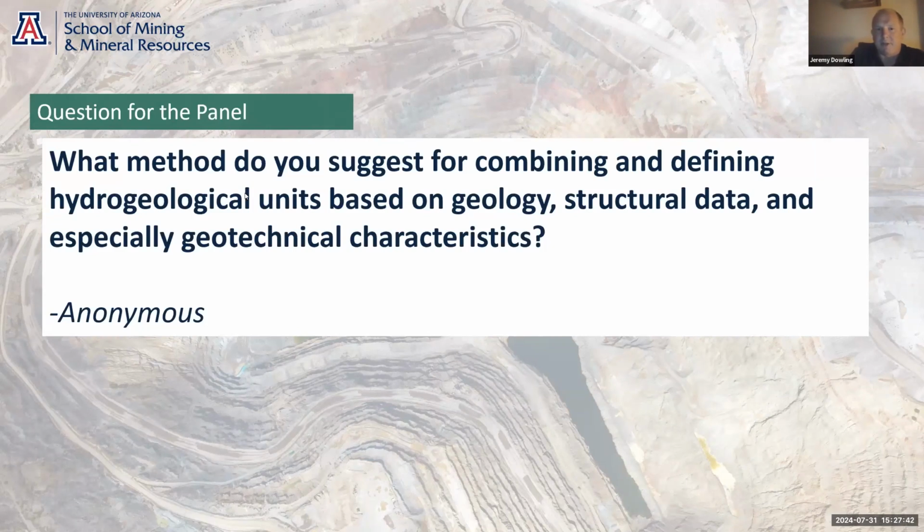So the thickness and properties of a fault, such as the fill material, presence of gouge, and the continuity that are geotechnically important, will often coincide with hydrogeologic properties of importance, such as barrier or conduit type properties. And then at the smaller scale, the orientation of structural fabric can sometimes be important to imparting a smaller scale anisotropy into the directions of permeability in the rock mass.